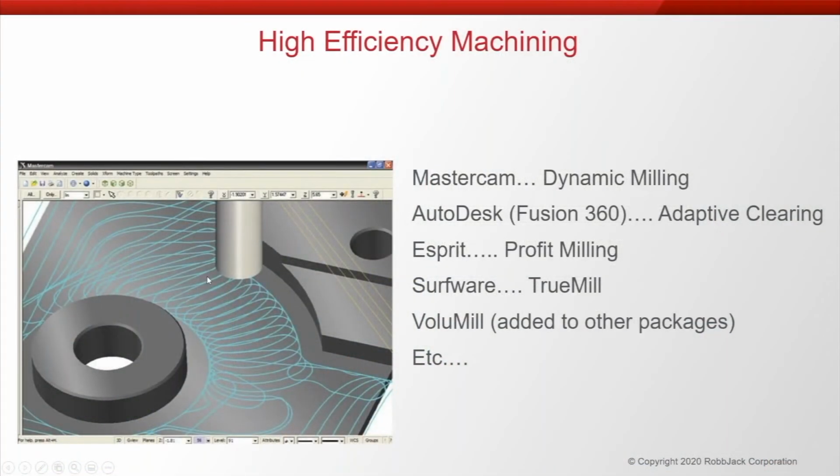So here's an example of a tool path. At the beginning, when CAD/CAM systems first came out with the Trochoidal tool path, it was really only good for something like what you saw, a slot, because there was a lot of wasted movement. Now they're all very hybrid type methods of doing this. So it analyzes it and it only does a Trochoidal cut when it needs to. And then it can do traditional types of cuts when it's not in that area. So you don't have any of that wasted air movement.